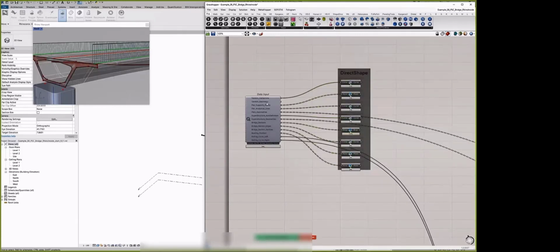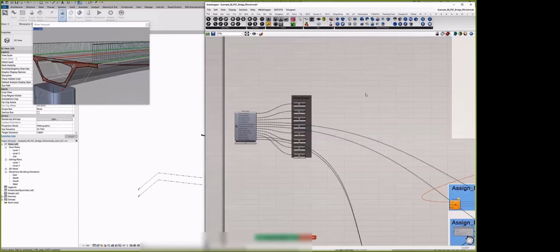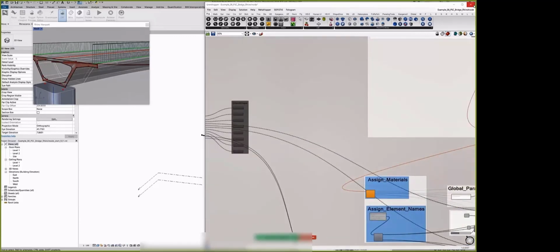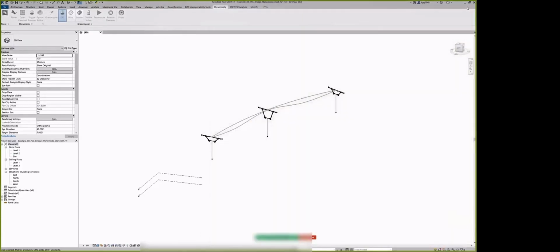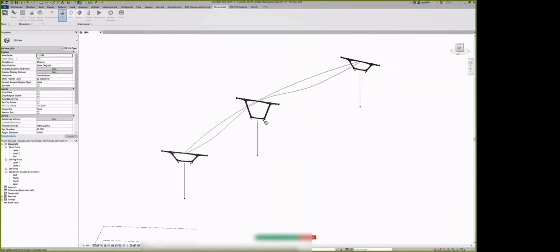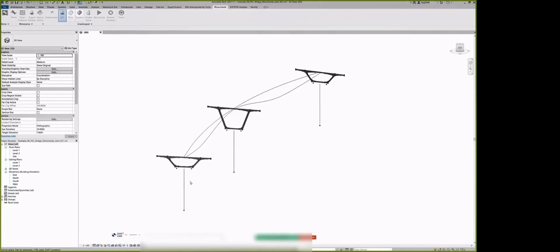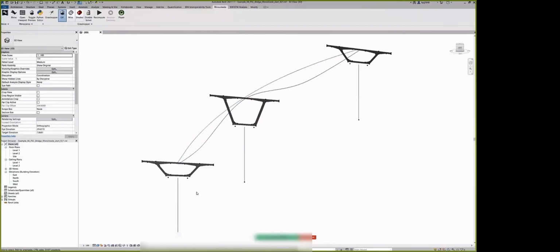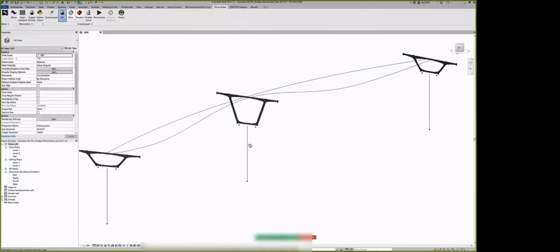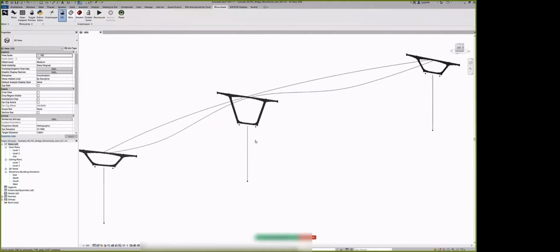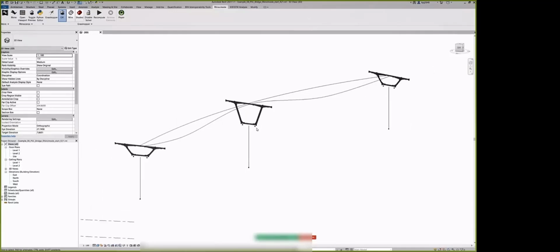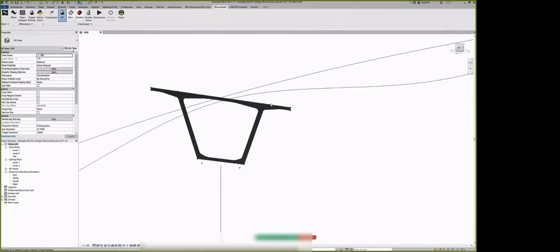And right now, I'm going to convert all these static elements in Revit from the Grasshopper outputs. So you can see we have cross sections of those bridges, and also the tendons, the cable center line, the pier center line, the bearing points, the support conditions, where support conditions should be, and all the annotation parts.